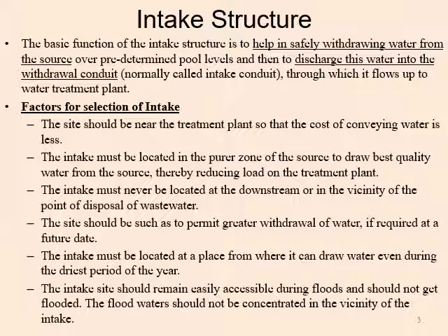The intake must be located in the purer zone of the source to draw the best quality of water from the source. So what will happen if we check the water quality from a particular site and it is then known to us the water quality is much purer than from any other site, then the water going next to the treatment plant will be purer.